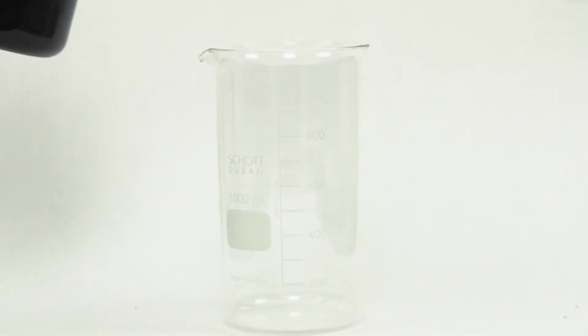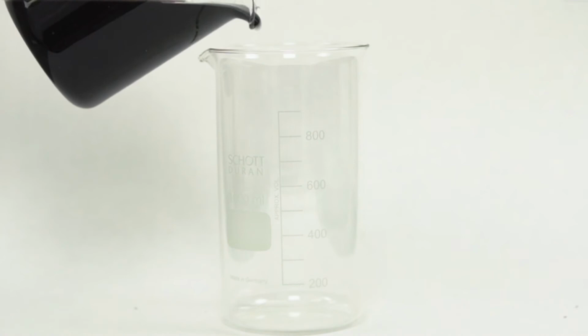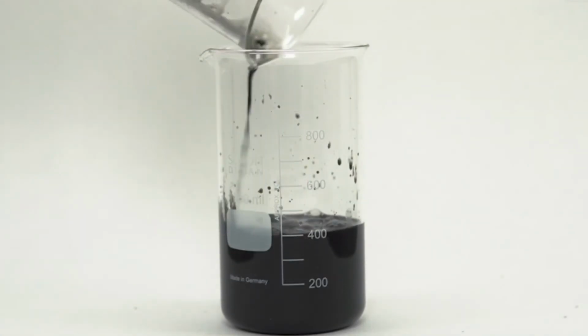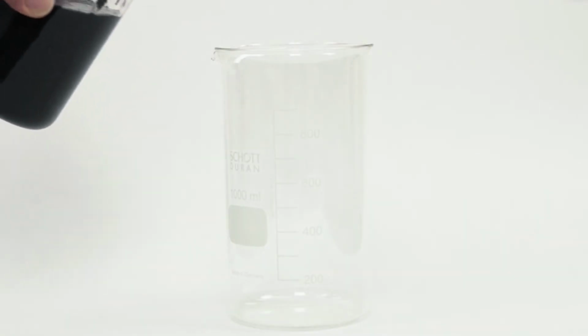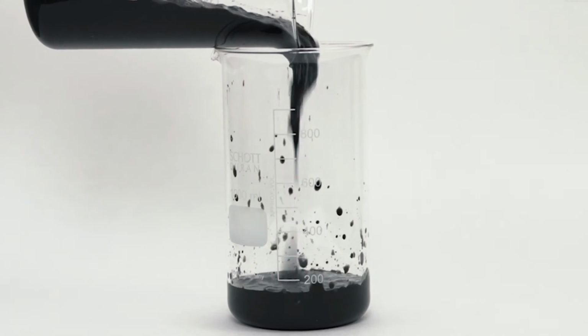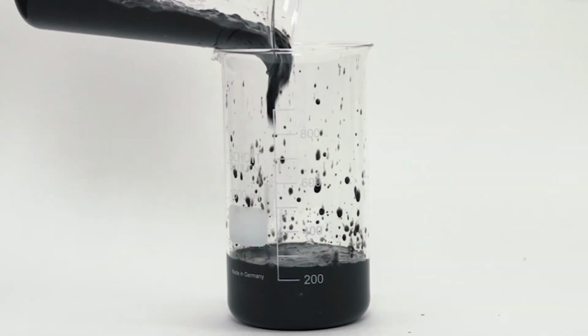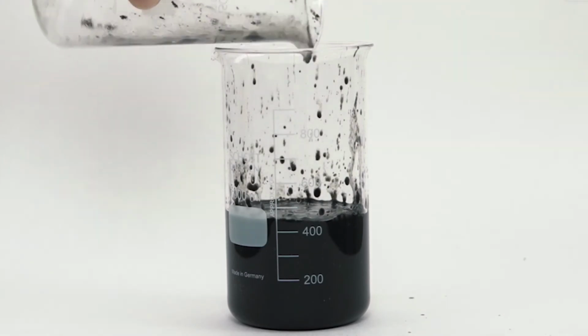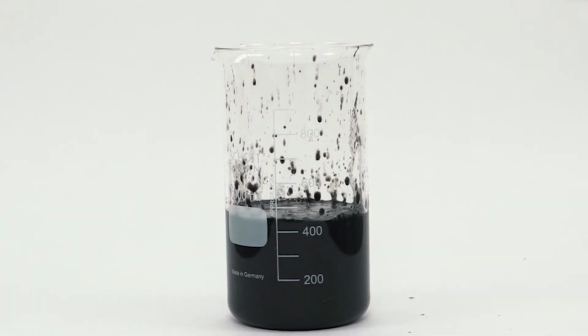The difference polymeric flocculants make is easy to recognize. Both of these jars contain sludge of the same DS content. Let's look at the sludge without polymers first. It's a very thin liquid with disgusting little lumps flowing out of the jar. In contrast, the sludge containing polymers looks and falls out of the jar like potting mix. Its viscosity has been increased by a factor of 20. As you can see, the rheological behavior is completely different, even though the dry solids content is the same.